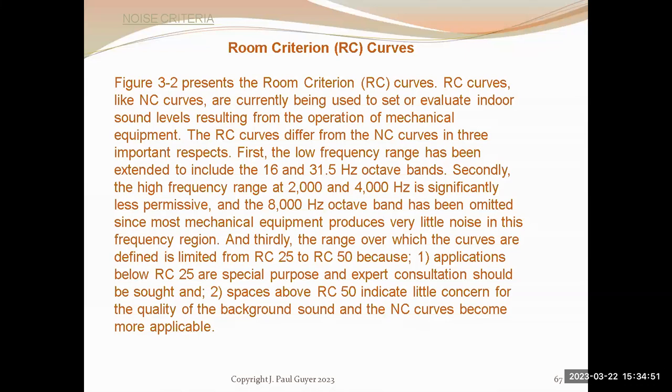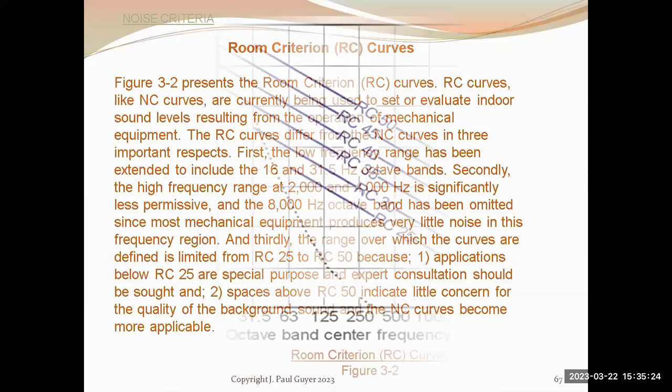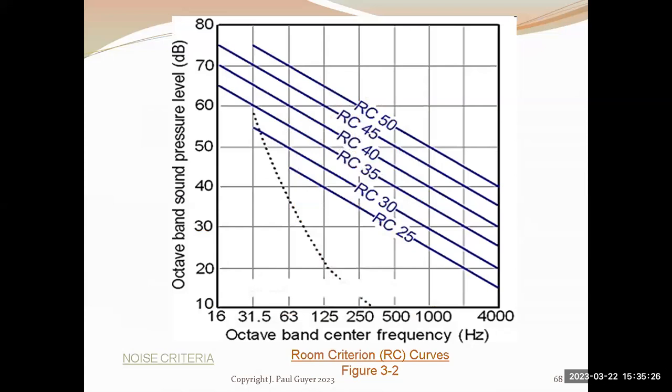And you know what you want to reduce that source room noise to in the receiving room because of the human activity that's going on in the receiving room. And you do that by constructing barriers, that is walls, ceiling, floors, etc. And that is, in simplified form, what you're doing with noise control.